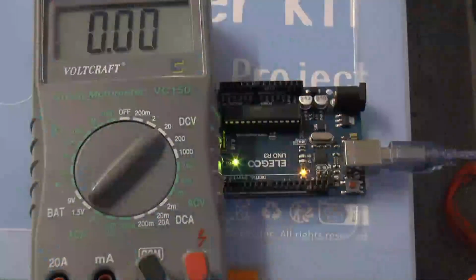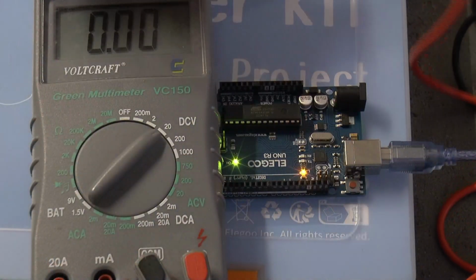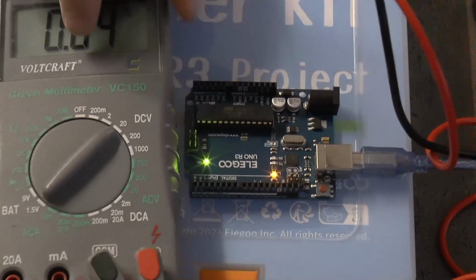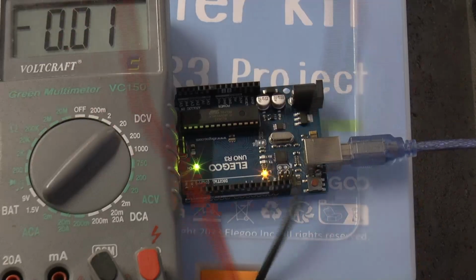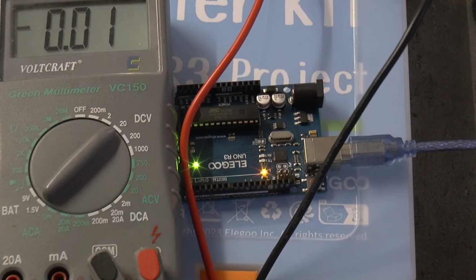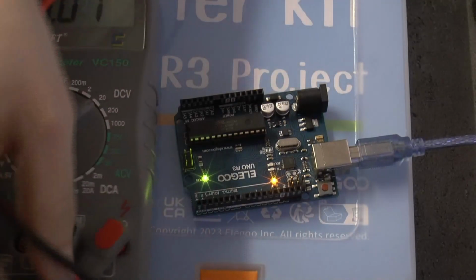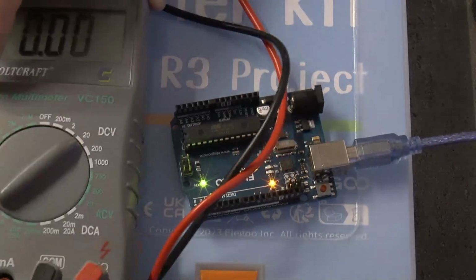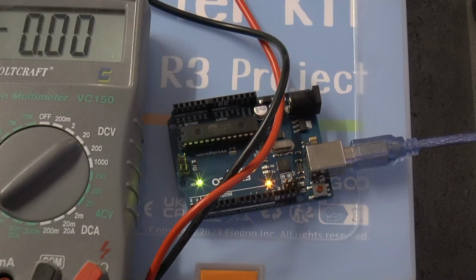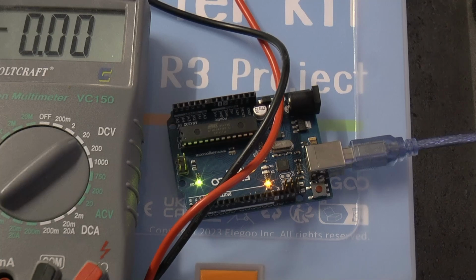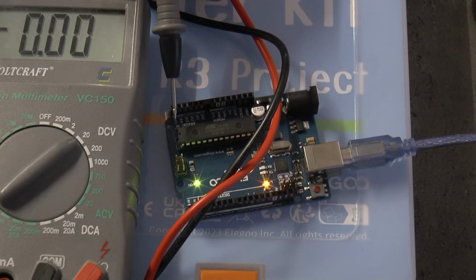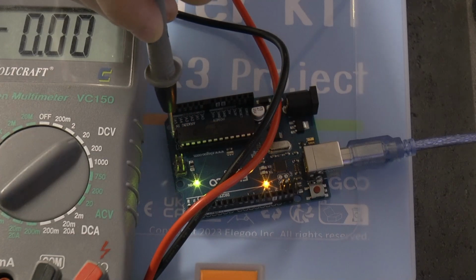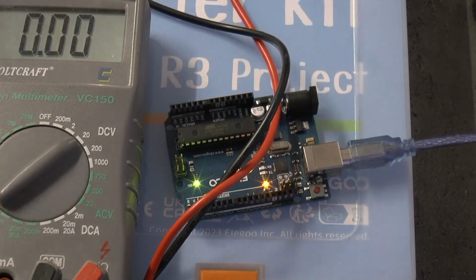And then if we go to the full screen, you can see directly next to the multimeter is the notch of the microcontroller. Now I'm pulling the microcontroller with the wires of the multimeter, which is not so cool. But I have my multimeter in voltage mode so that it measures voltages. And what I now want to do is poke the pin 8, which is the ground. So pin 8 is starting to count from there. This is the first pin. We would need to count to 8 there.